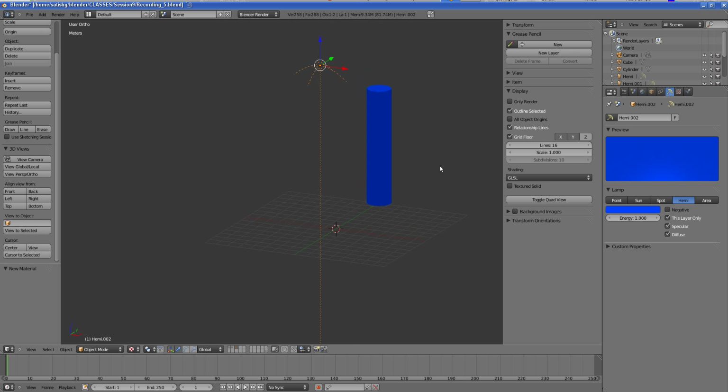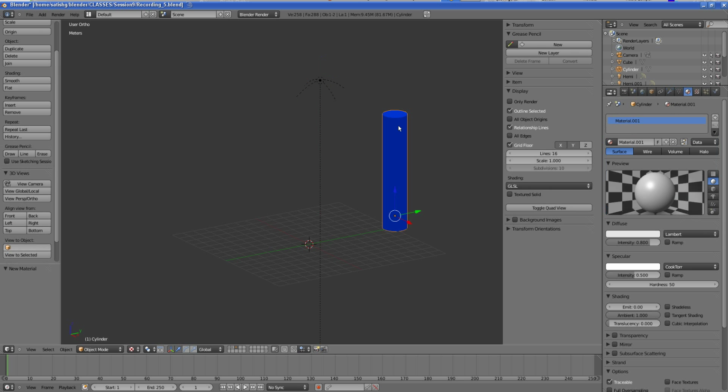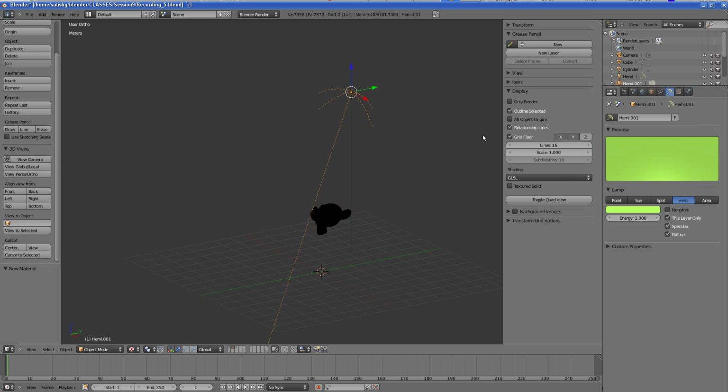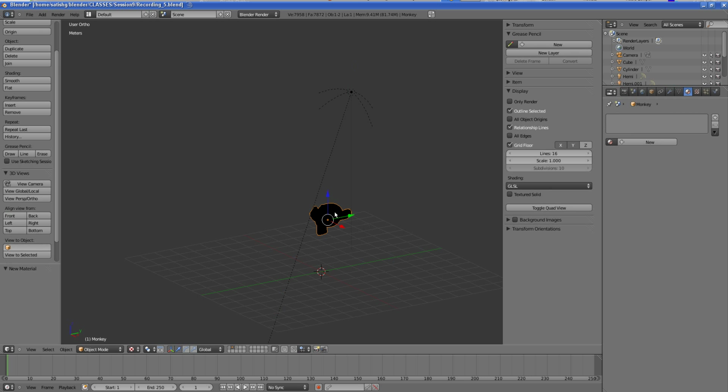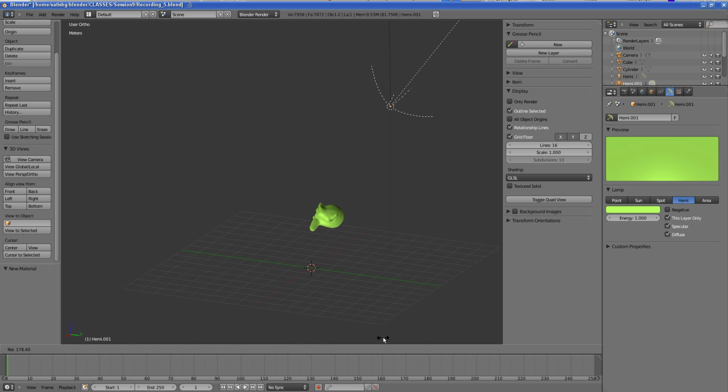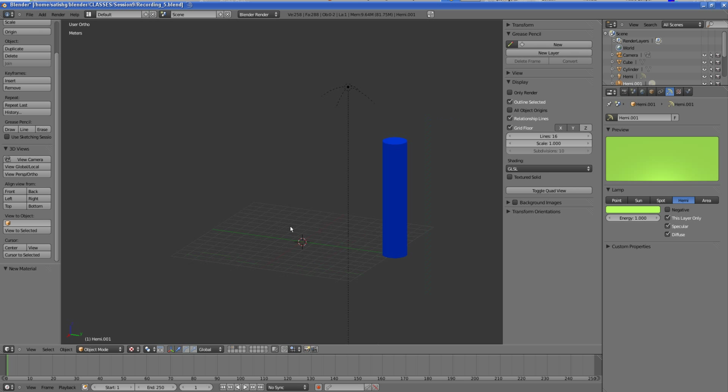In order for you to visualize the effect of this hemi lamp in the textured and GLSL shading mode, the geometry object should have a material assigned to it. You'll notice that my Suzanne mesh doesn't have a material, so that's why in the textured mode and GLSL I don't see the green color. So I just select Suzanne and add a new material, and voila. Now you can visualize. I'm glad I found this during the tutorial.